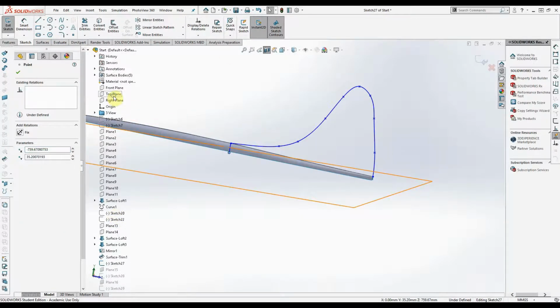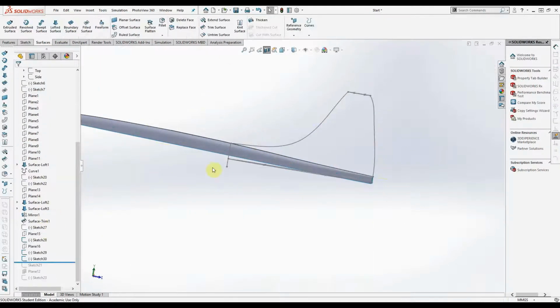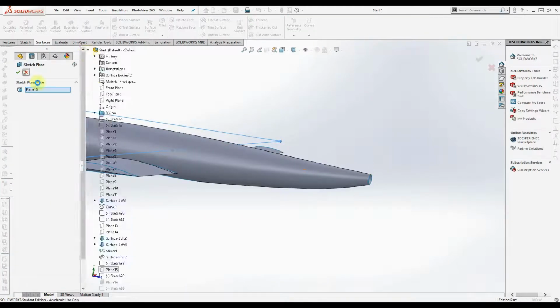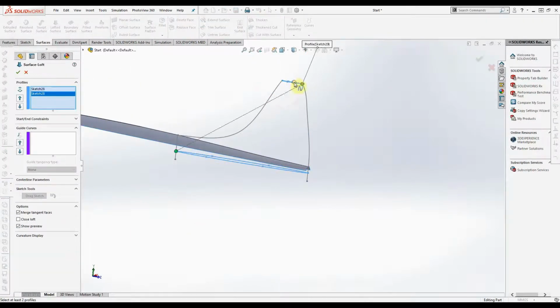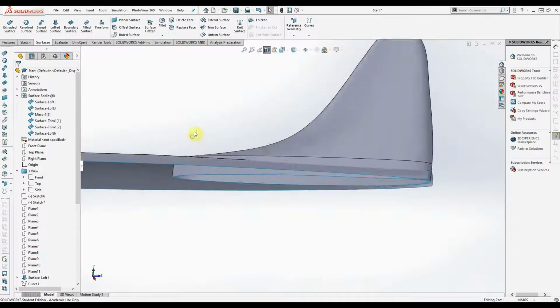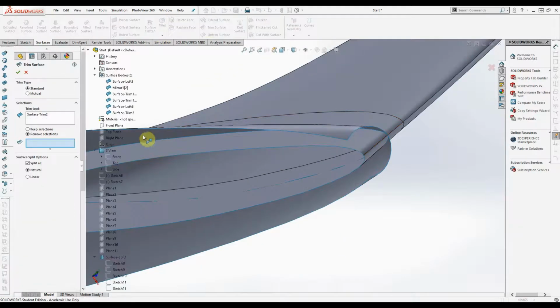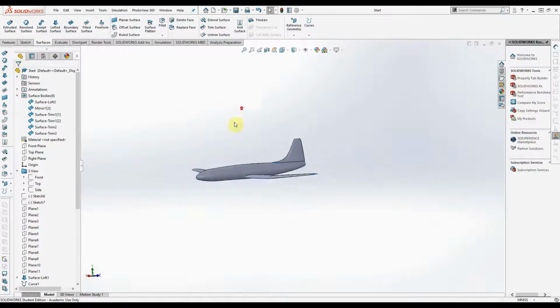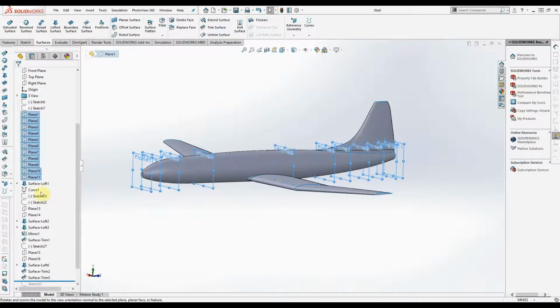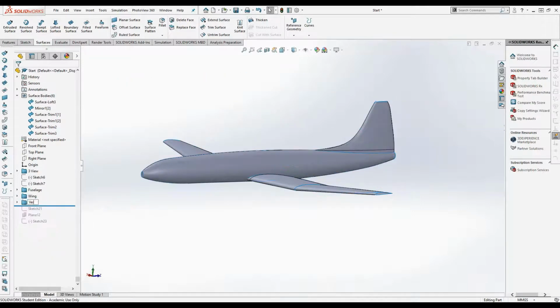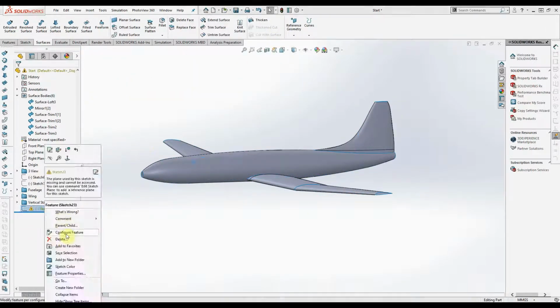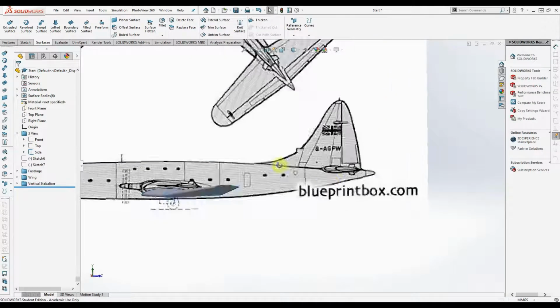So here I realised that because the fuselage is cylindrical, I actually need to move that plane down slightly. This lets the sketches intersect, and I have a full intersection of the surface model. And here I can trim it out, and it still is flush without any gaps. And then I'm just going to put this all in a folder to keep them organised.